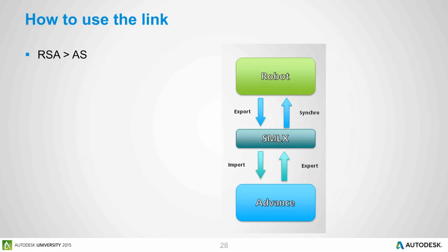Mind that for a group of connections created in Advance Steel, you should name the connection with the largest forces as the master, because there is no code checking for forces imported from a model for slave connections. For example, for secondary beam to main beam shear connections, make an envelope of shear forces for a selected group of elements in Robot to determine the location of the master joint. Let me show how it works.